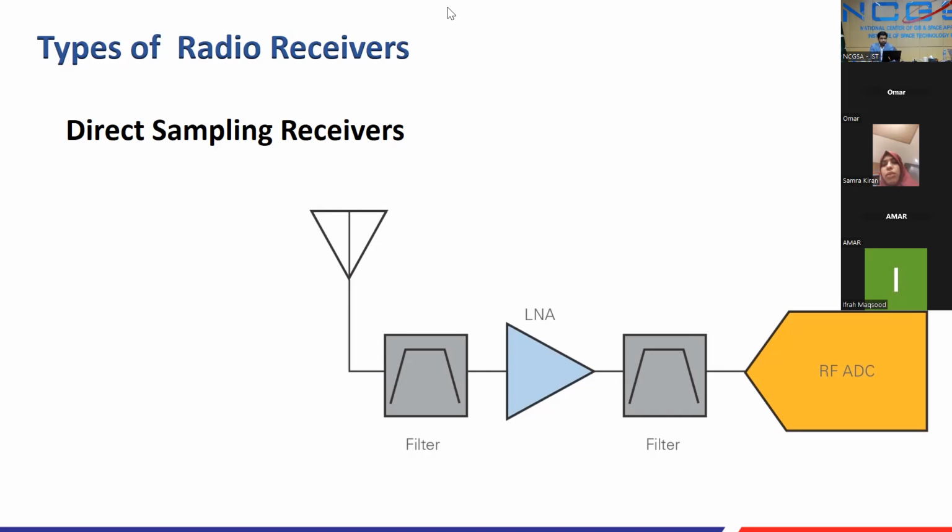Okay. I have another question. Can you state the values of ADCs? How many samples, what was the rate of ADC which you used in your specific design? I cannot state explicitly, but I think 4 gigasamples per second for direct sampling. For the other applications, I think generally we have 1300 MSPS, 1600 MSPS, based on which application. We make a lot of systems, so those are different applications.